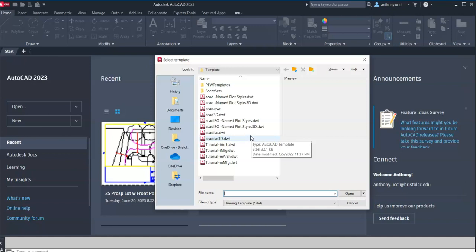So first thing you got to decide, is it inch or is it metric? And if you take a look at the drawing, you'll see that all the numbers are whole numbers, right? They're dimensions like 70, 60, etc. If it's in whole numbers and rather large whole numbers, you know it's going to be metric, right? Because, for example, the size of the ellipse is 70. If it was inches, this would be a part that was almost 6 feet across. So we know that's probably not right for this type of part. So this is metric. And like I said, whole numbers, it's going to be metric. When you're dealing with inches, it's going to go to 2 decimal places.